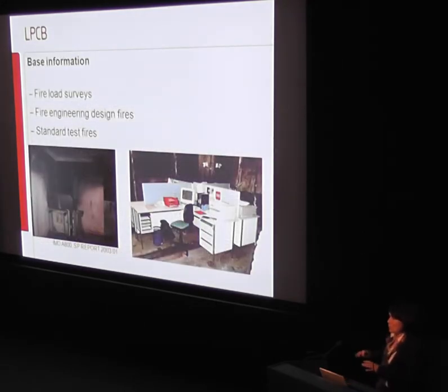The other thing is that water mist is very application specific. So we were trying to find a way of moving more to fire engineered values for it. You could look at fire loads and determine a mass loading of a space and try to relate that to the use of a water mist for equivalent spaces with the same mass loading. We've got a database of design fires where we've run many different types of fires and looked at the calorimetry problem.